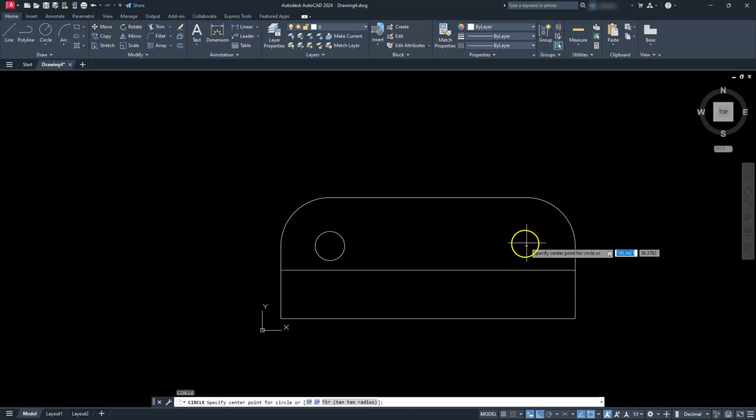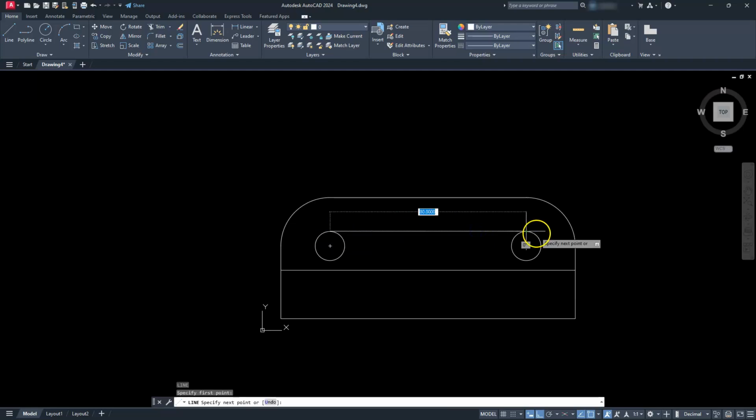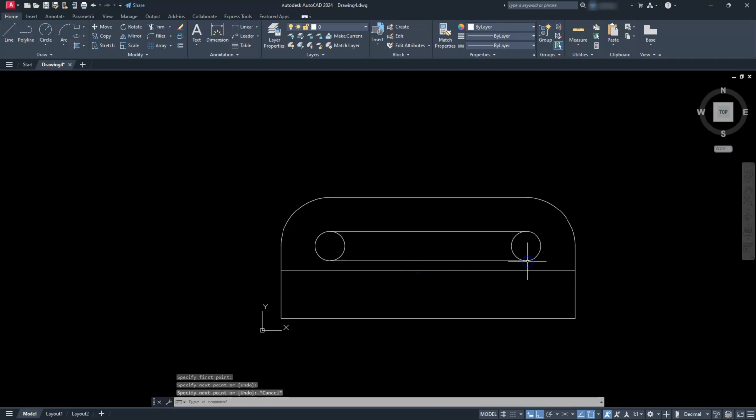Then I'm just going to touch this and then come to the center here. Do a left click. Kind of always preview my circle. And since it's the same size circle as my last one, I'll just hit enter. I'll draw a line from this quadrant over to this quadrant. Escape out of that and repeat the line command. So line from this quadrant over to this quadrant. Let's go ahead and trim.